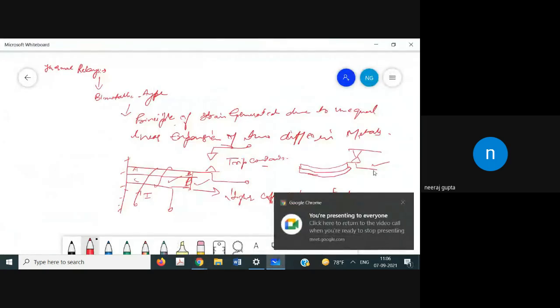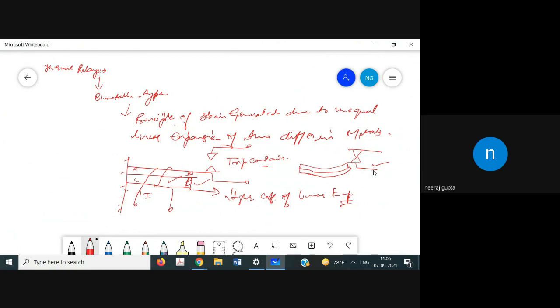Now, the accumulation of a sufficient amount of heat depends upon the thermal inertia of the relay, which tends to be large. These relays are used where very quick operation is not required.